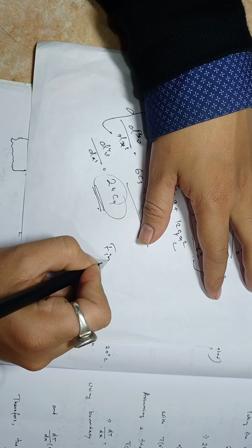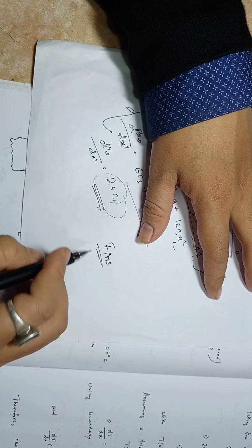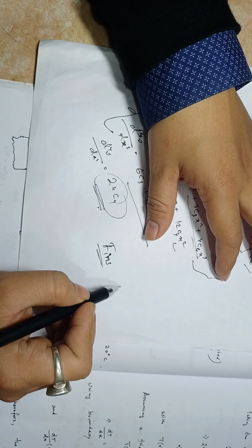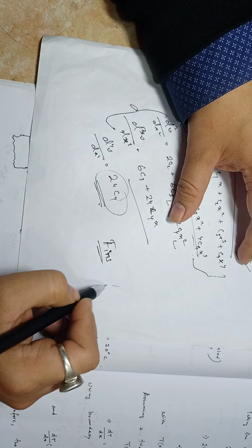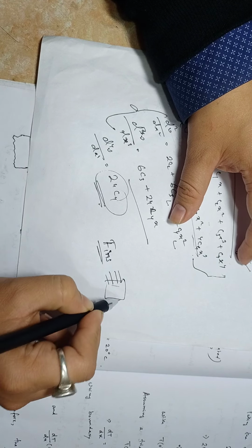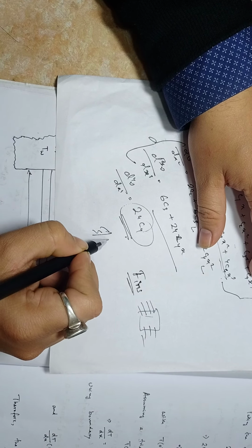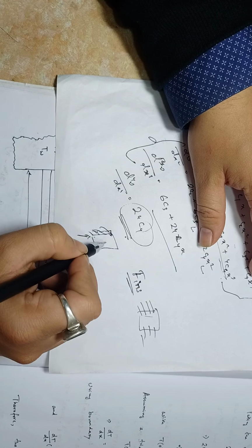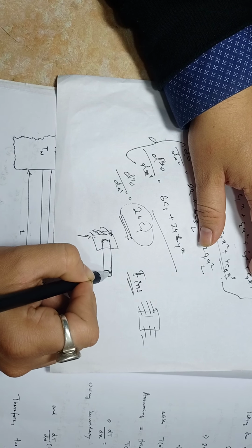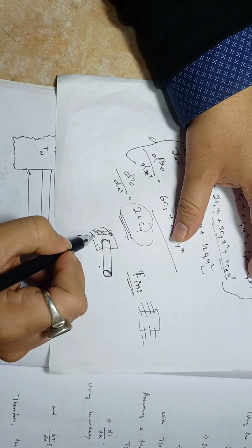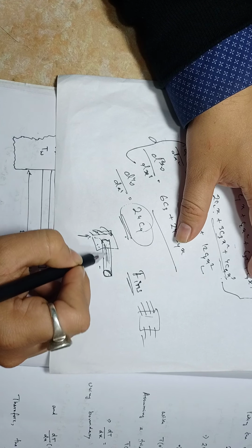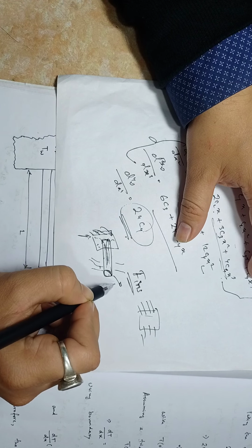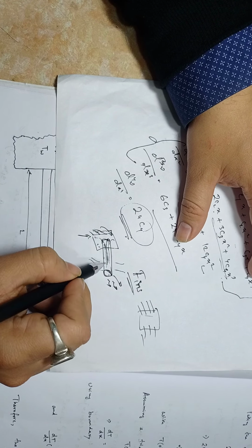Fins are used to release heat from a heated object to the atmosphere. In bike engines, you have seen fins, right? These are the fins. Here, for a pin fin, we have something from where heat is being generated, and from there we have a circular structure like this. Obviously this is the conductor, so heat will be conducted through it, and air will be flowing over it, so heat will be dissipated to the air.